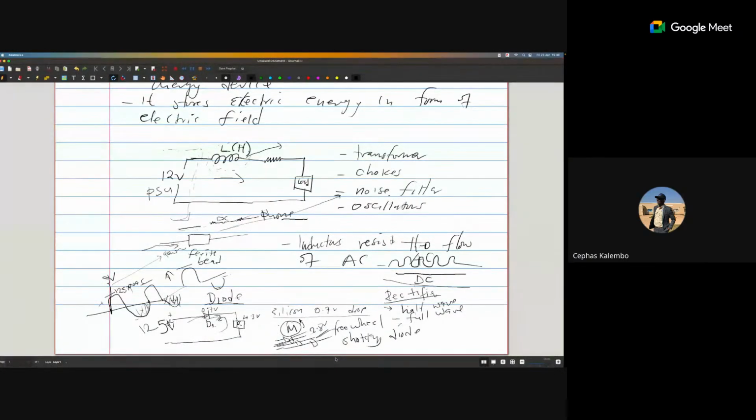For an application where you precisely want voltage control, the diode you would want to use is a Zener diode, or basically just a voltage regulator such as a linear dropout voltage regulator. But in a situation where all you want is to drop the 0.7 volts and the device you want to power is not sensitive to voltage fluctuation, yes, you can use a diode as a voltage dropper.